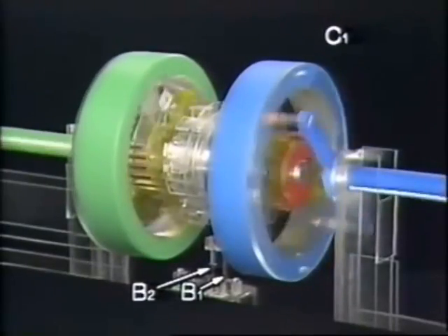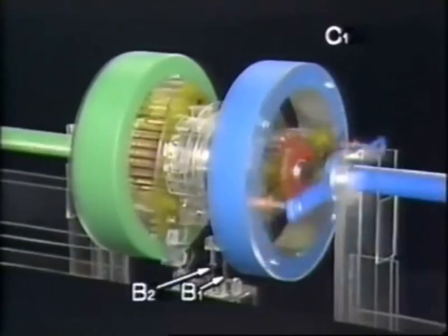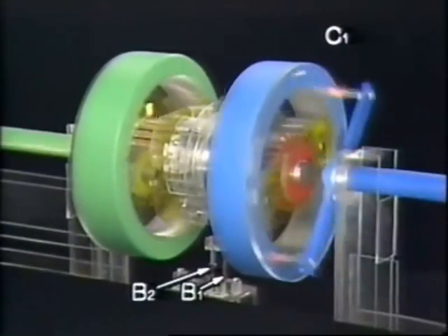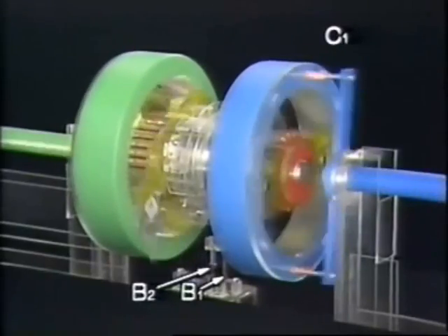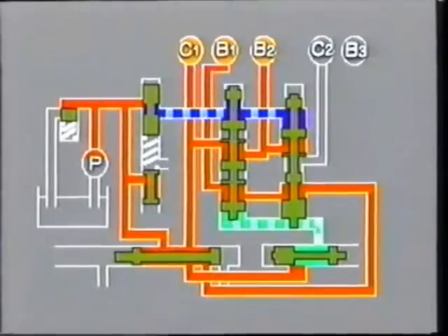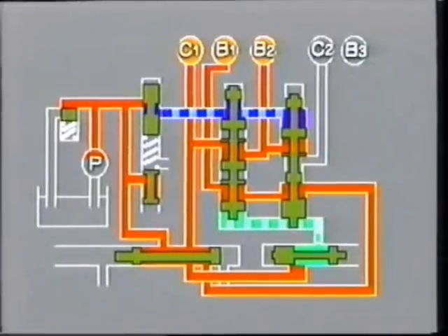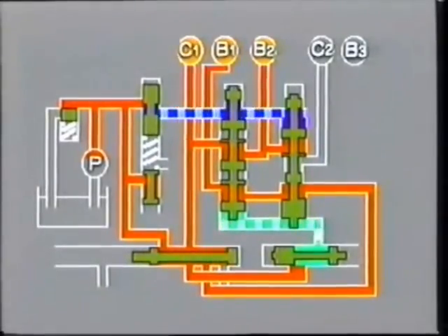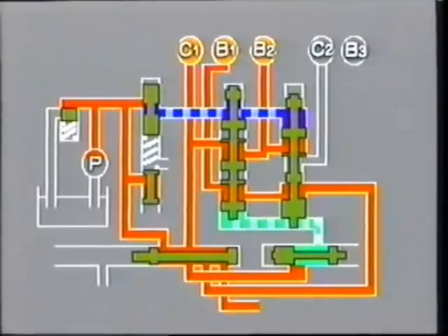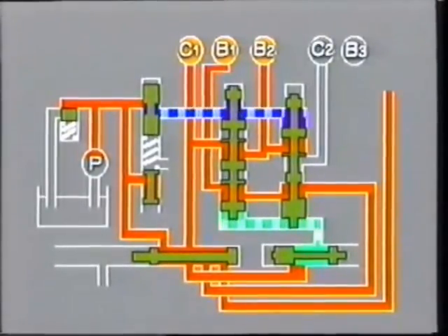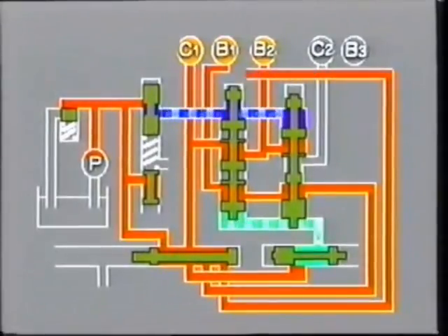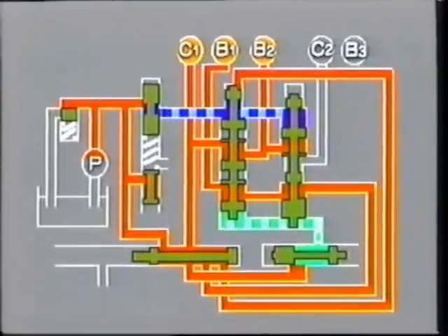In second gear of the 2 range, the sun gear is prevented from turning in either direction by brake B1, so engine braking occurs. In L range, a line pressure passage is also opened up above the 1-2 shift valve, preventing upshifting into second or third gear.